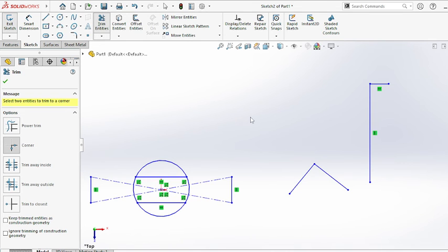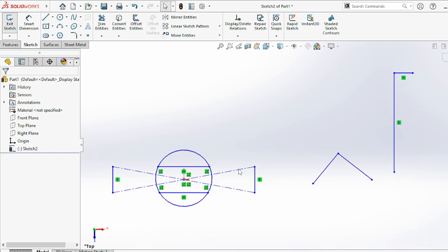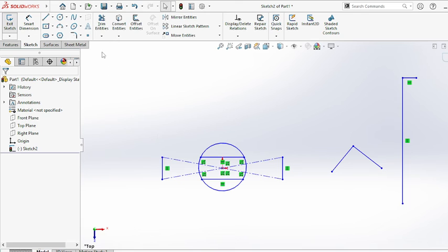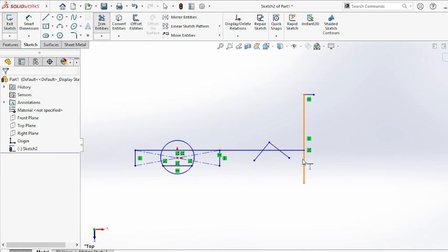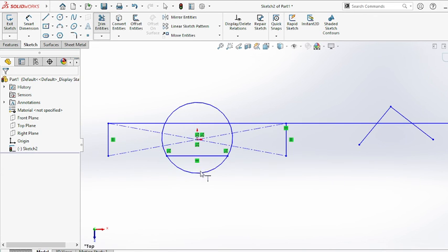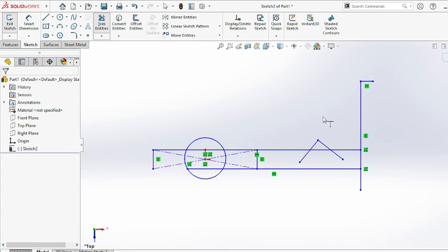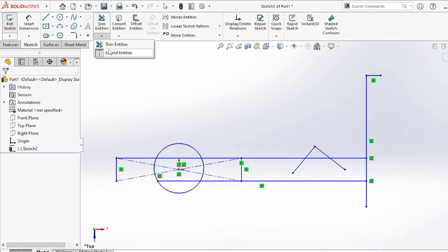So next one, extend. Why have to use extend command in AutoCAD? You can extend the lines. You can go to the extend command, select this, you can extend it. Select this, you can extend it up to here. Select this, up to extend it. You can select this, extend. After selection, this extend is possible now. Why? There is no endpoint here. Okay, select this. You can extend only lines.